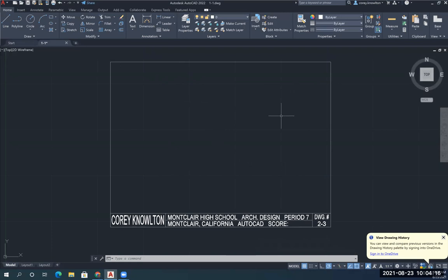I have given the instructions on the back of each of the drawing assignments, the written instructions, but if the written instructions don't make sense, or if you're doing this from home, then I'll give a demonstration on it right here. So the top left corner says that we're going to be drawing lines with ortho on and with ortho off. So before I start this one, I'm going to make sure that I have snap turned on. So grid and snap are on. I'm going to turn on ortho because it says we're going to draw lines with ortho on and ortho off.